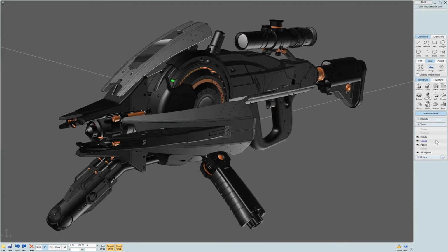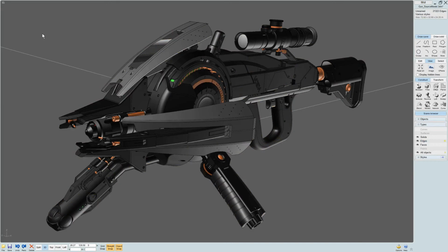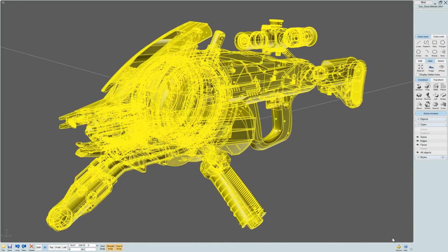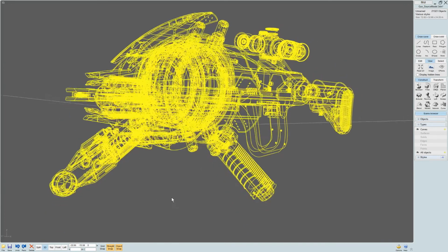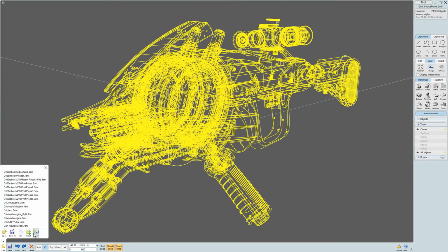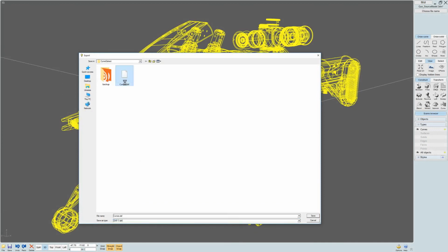We can also try to export the curves only, just to try something in Houdini, like just selecting the edges, Ctrl C, and Ctrl V. We can export them as polylines using the DXF format.